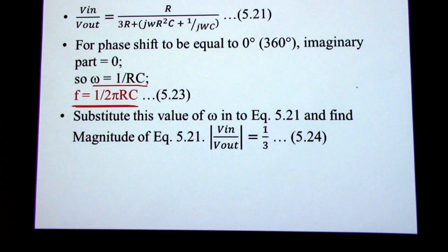And we also need to figure out the magnitude. So if you apply the Barkhausen criteria, you see you get 1/3 of your input. So naturally speaking, you just have to have something that gives you a gain of 3, so that ultimately you have net gain of 1. It just sustains.